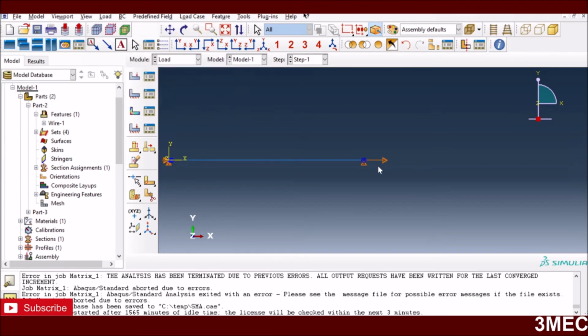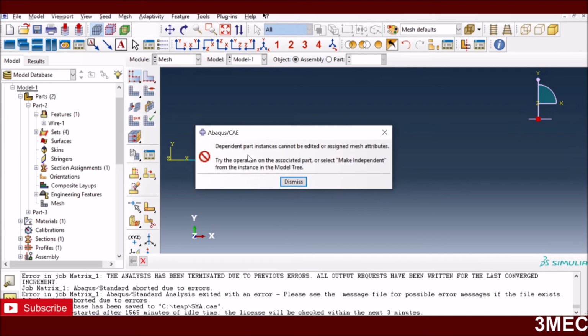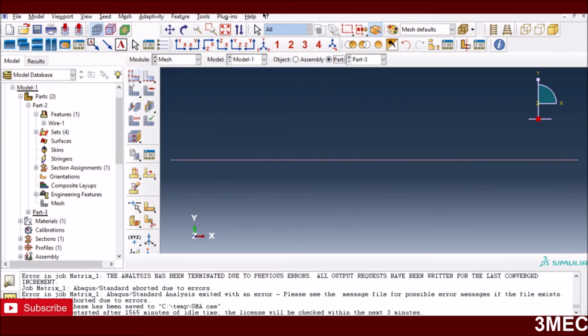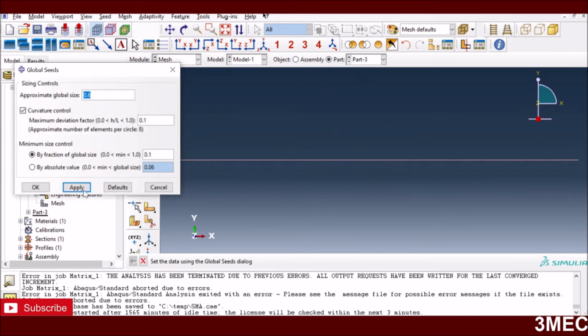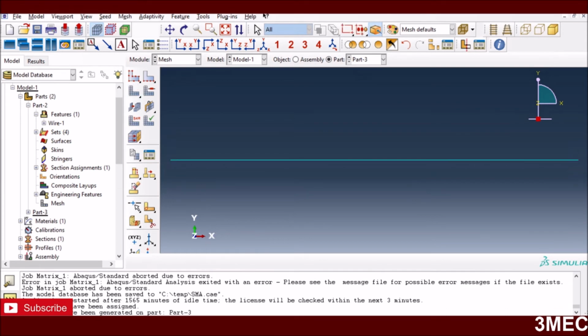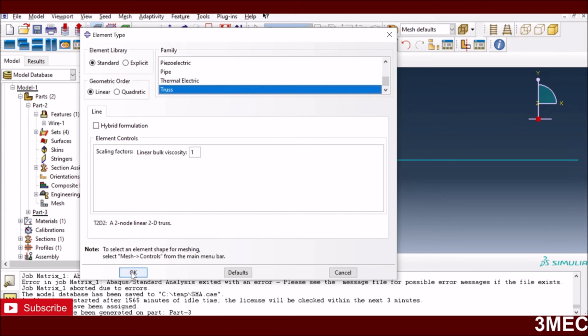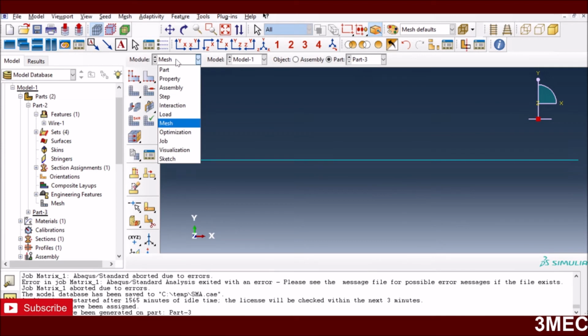So this is what I have done here. It goes like this and then comes back to 0 to capture that cyclic effect. Meshing, I only use one element here, so I just say the total length is 1. So if you see here, this is only 0.6, so I will have only one element here. Okay, and then I mesh it. So you can see I have only one truss element, and if I show you my truss element, it is truss and it should be okay.